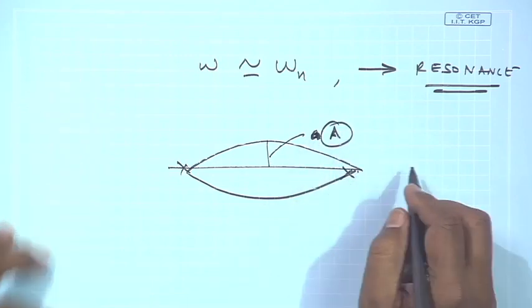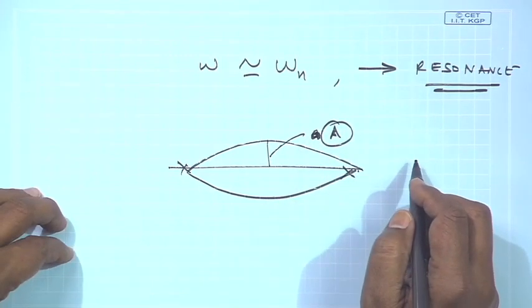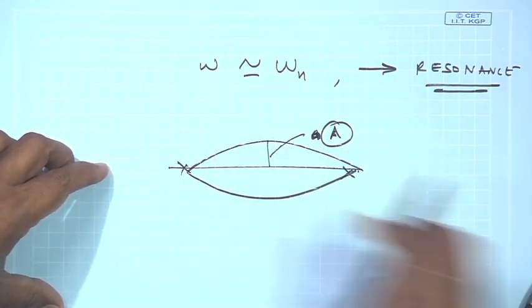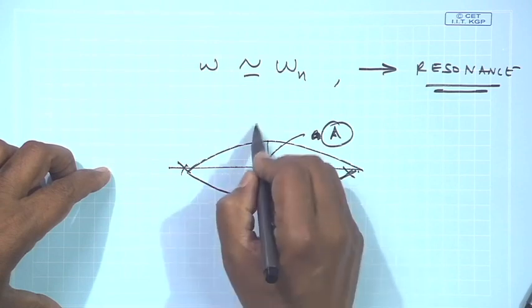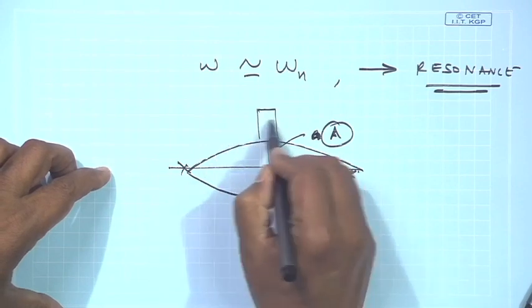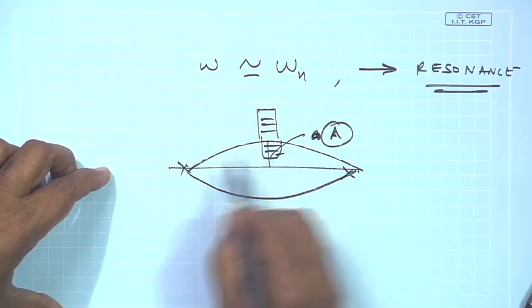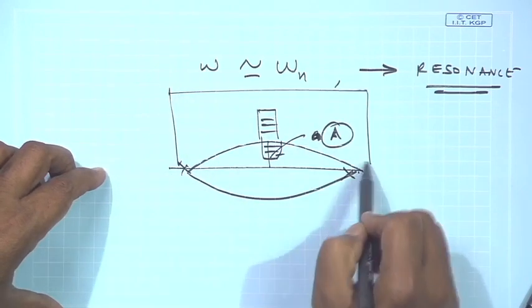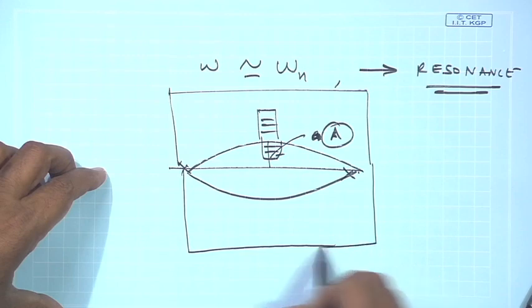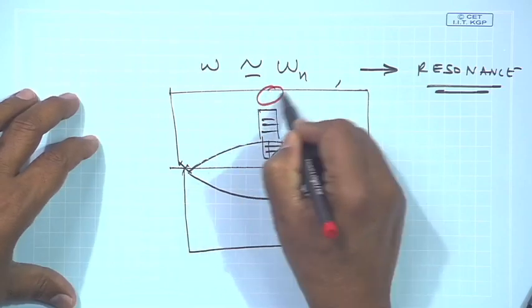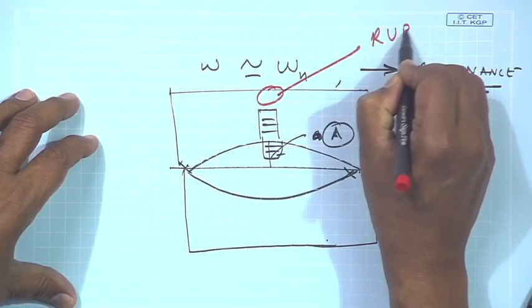There are many reasons why this amplitude has to be under control. Imagine if this was a long shaft carrying a set of blades, and it came across a casing. Once it touches the casing, it will give a phenomenon of rub.